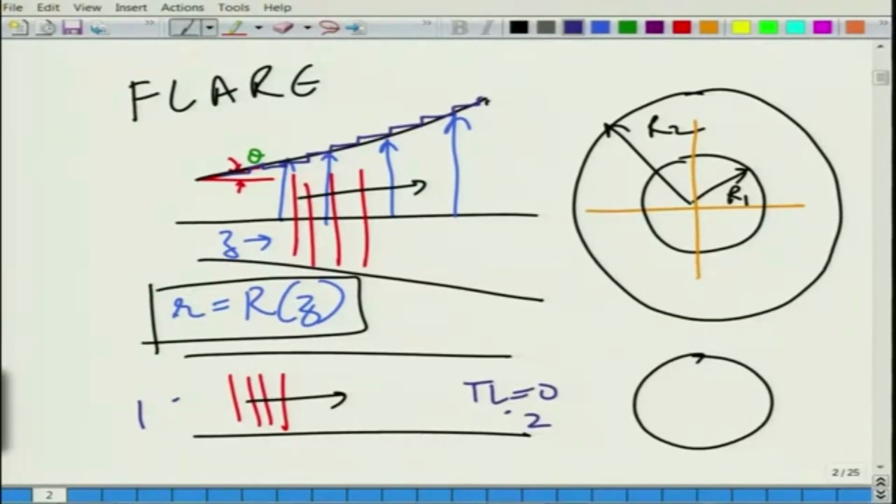However, it is quite intuitive to think that for a gradually varying area, the transmission loss, or basically the acoustic power that is reflected back as the wave propagates from 1 to 2, will be non-zero. Forget about introducing sudden area discontinuities like an inlet and outlet port.